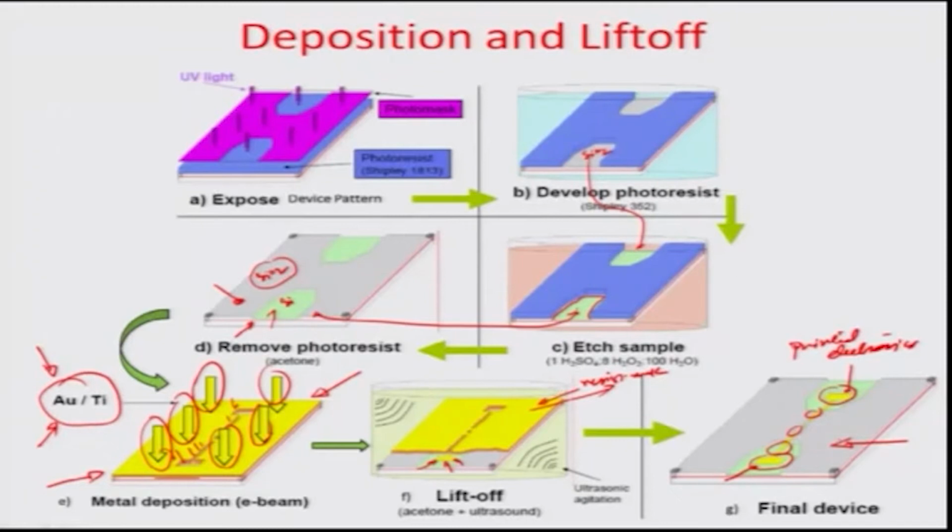So with this photolithography and a combination of various processes, like in one case you saw the etching process, how it combined with the lithography. In another case you saw the deposition process, which again combined with the lithography, and then the lift off process. You are able to generate various micro machined features or micro machined structures by assembling these processes together. So these are one of the most advanced, first generation advanced microelectronic processes through which you could achieve structuring or featuring at the micron scale.